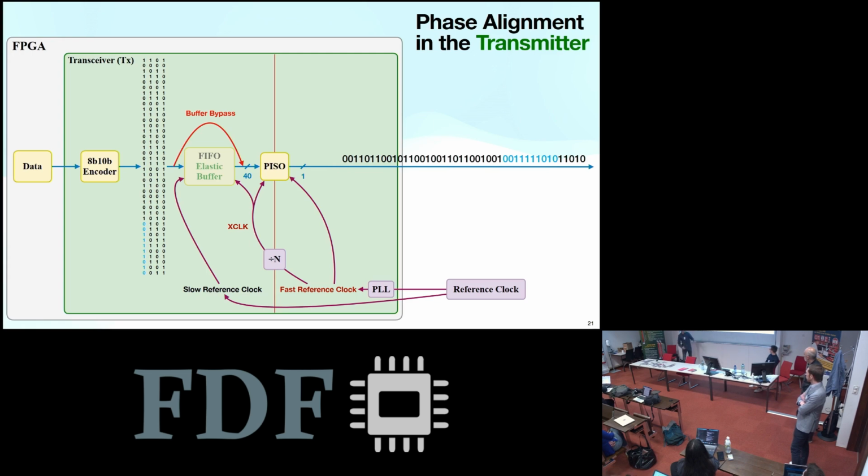So this slow reference goes also in a PLL, but the frequency doesn't change, so the phase doesn't change. But to generate our clock to sample the serializer, we need to multiply. No, because this goes out at gigahertz. So that is why we lose the determinism. If you say you lose the determinism, no, I have never observed any problem with the synchronization. Whatever you are writing to the TX parallel buffer goes out synchronous, and it's always synchronized to the TX user clock.